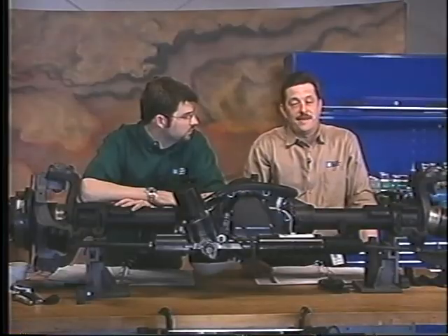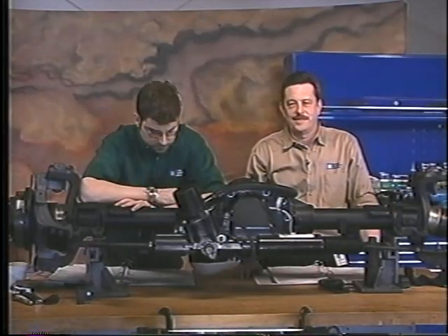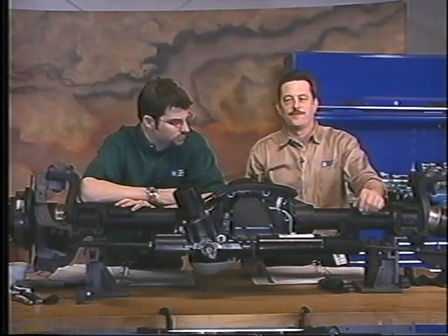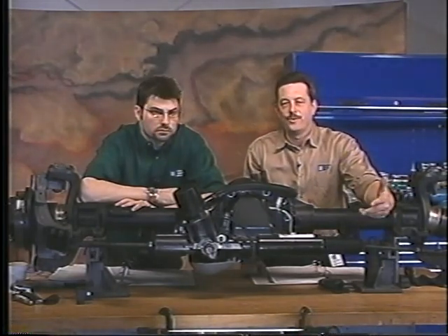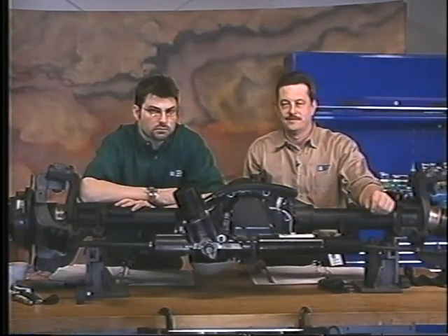Okay? All right. About tire size. The other thing to really talk about is tire size. Don't change tire size on these vehicles. It's just not worth it. Too much going on there. We're dealing with the software in the module to deal with that. We're also looking at the PCM software, looking at ABS software. You've got to make all three of those match. And it's just not a good idea.